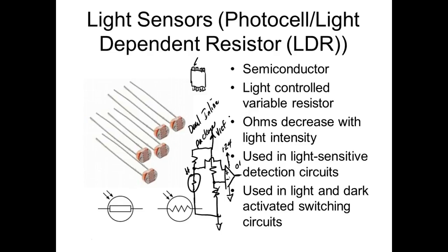So what that means is it works okay for a light of day sensor because the light varies real slow. So these guys here work great on that. We probably wouldn't use these on an electronic flash on a camera where it's trying to measure the amount of flash it puts out, because your flash is just there. Okay. So that means we had to come up with something that was extremely fast.